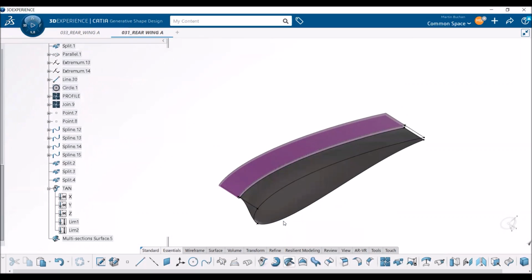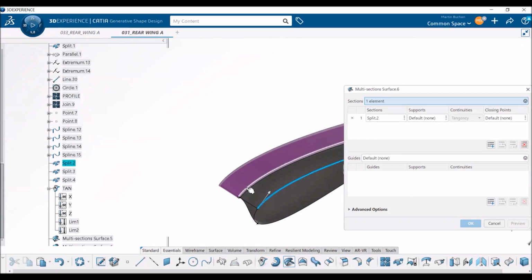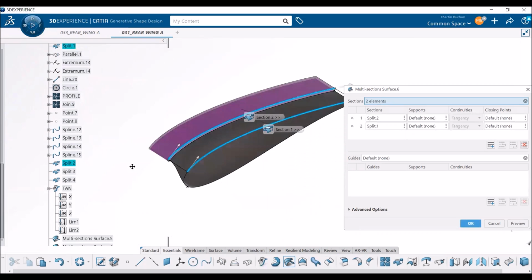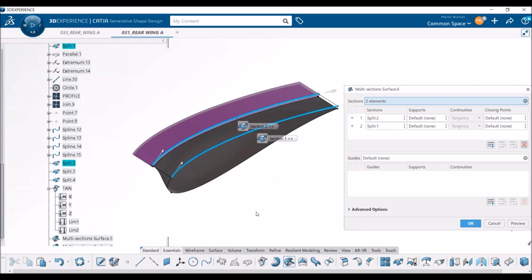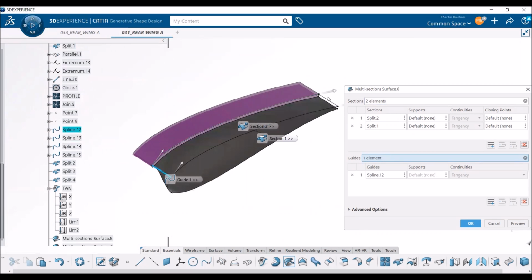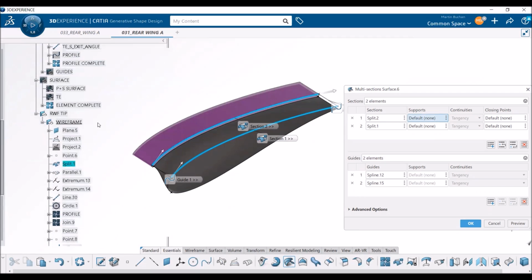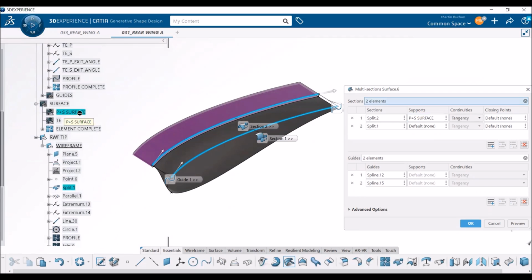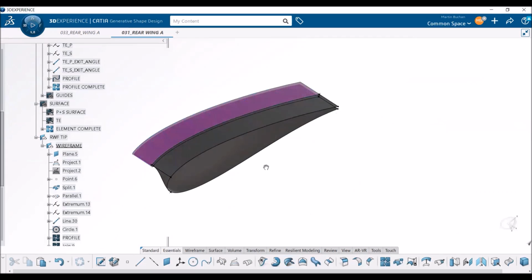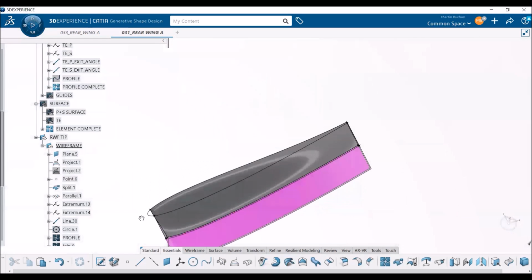Because the leading edge is a pretty stressed surface, pretty twisted, and it would need some good supports. It wouldn't create a good surface if you build the leading edge first and then build suction and pressure side. It's usually better the other way around. So build some unstressed pressure and suction side, and then build the leading edge using the other two surfaces as tangency surfaces. So here for the lower one it's the same thing, same tangencies, and that's it.